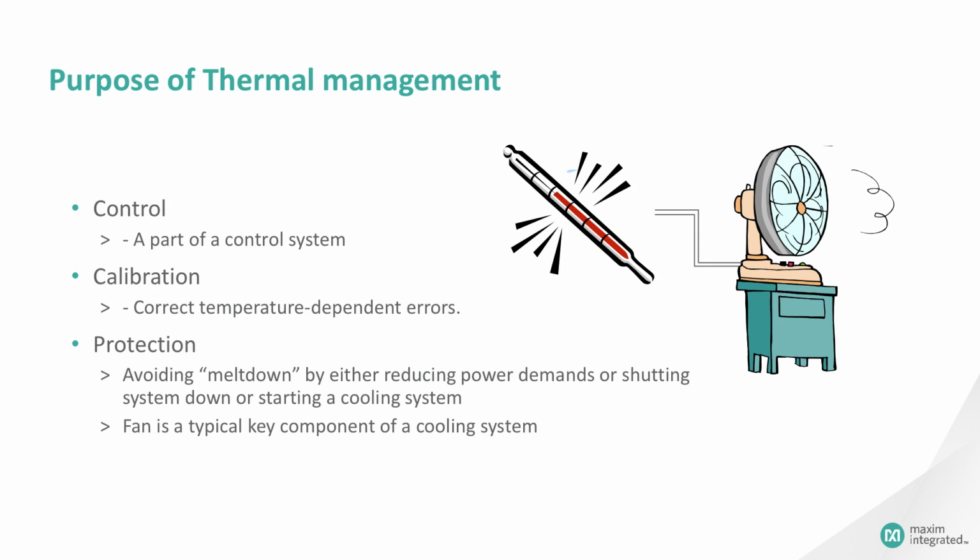For example, a TCXO uses temperature to adjust the operating parameters of a crystal oscillator to compensate for the shift in the crystal's resonant frequency over temperature. Signal conditioners for sensors, such as pressure transducers, use temperature data to correct thermally induced drift in the transducer's characteristics.